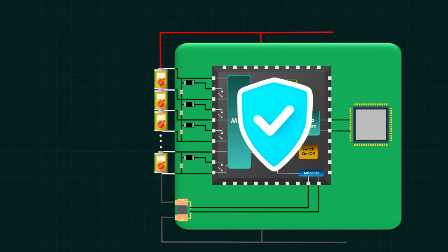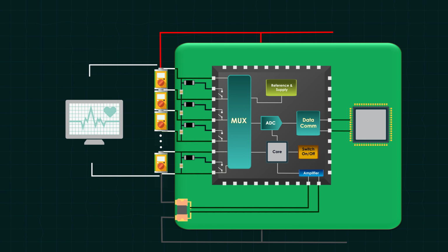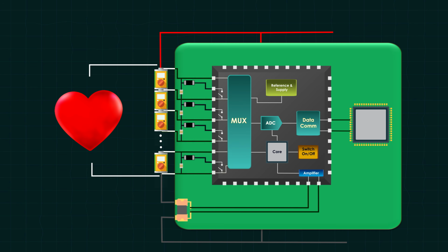The AFE is a frontline sensor and safety interface between the battery cells and the rest of the BMS. It reports cells' health status to keep the battery safe and happy. And as we'll see, a well-designed AFE is critical for battery safety and performance.